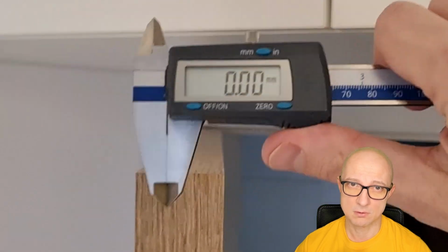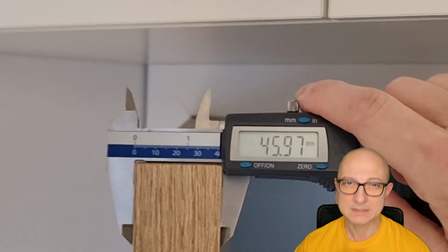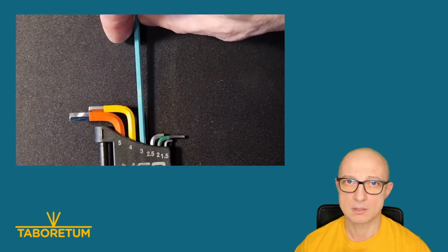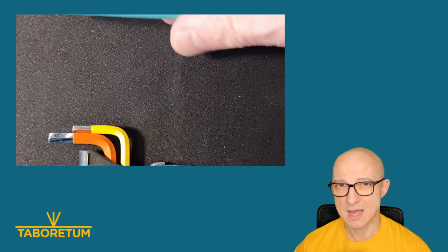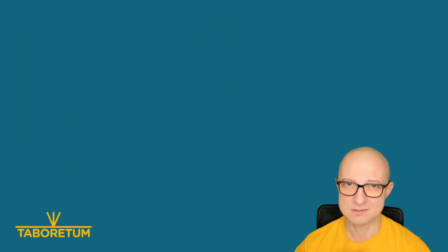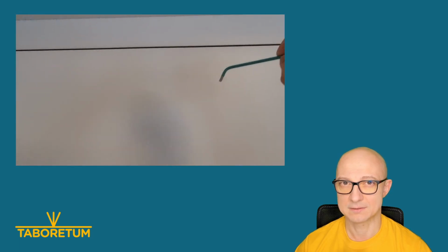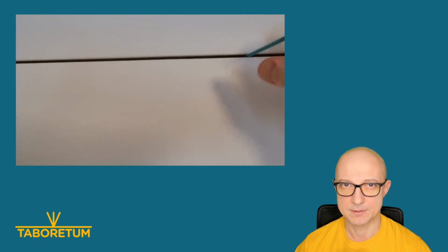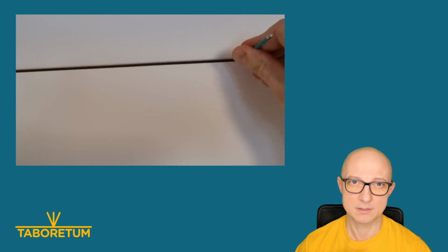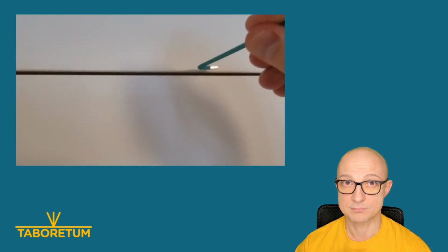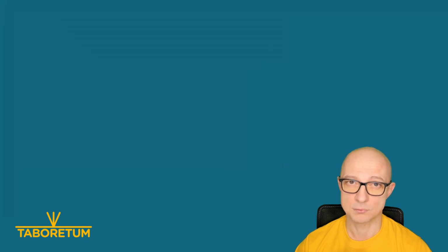The only thing you need to do is to measure the width of the door, as I did here, plus measure the clearance between the door and the frame. And I used an Allen key to do that. So with the doors shut, I just took an Allen key that fitted inside. So I know that 3 millimeters is the max that I can do. So I will design it with 2.5 millimeter, and the width of the frame will be 41 mils.